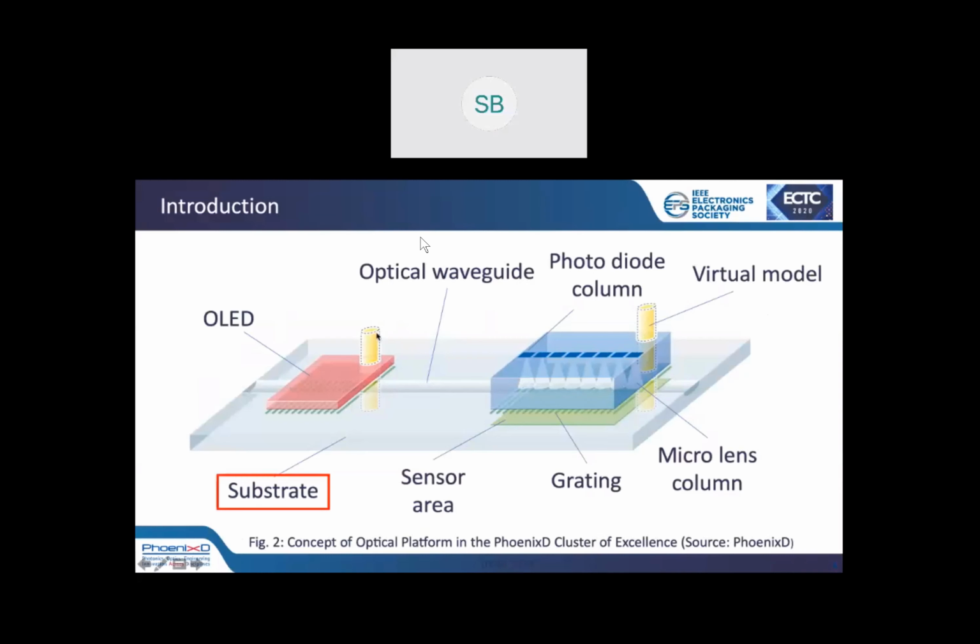We have different sorts of steel, for example, low alloy steels and stainless steels. The low alloy steels will be polished in-house using CMP. The next steps are common lithography and electroplating process steps to create nickel electroplated structures, which will imprint into the injection mold specimen.